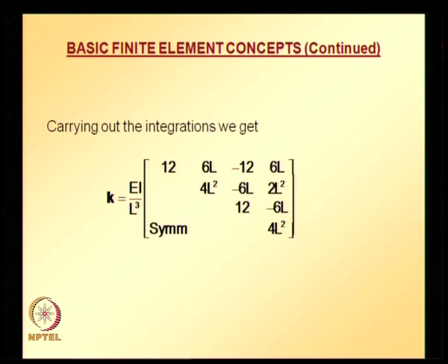If you recall from your matrix analysis of structures course which you must have taken, this is the kind of stiffness matrix that you arrive at even using any of the matrix methods, and the same thing we obtained starting with a finite element beam formulation and also starting with the variational approach. We derived the potential energy equation and then we substituted the transverse displacement, the derivative of the transverse displacement in terms of finite element shape functions, and finally after simplifying we arrived at this one.